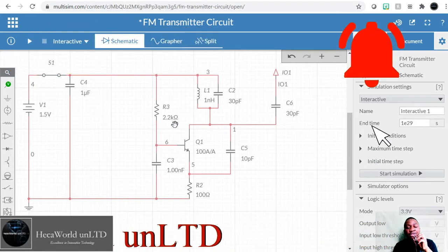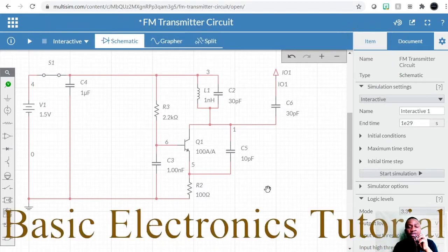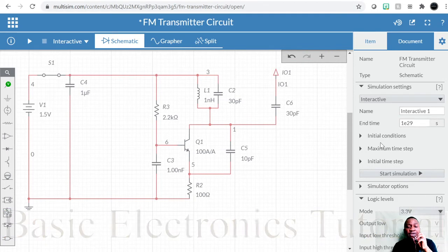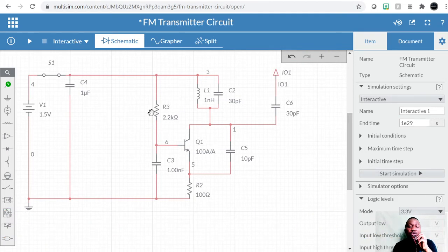The most important thing here is that you bias your transistor. So do this the way we did it. When we did it the first time, we didn't have this simulator, so we used a 10 kilo ohm trimmer resistor here and trimmed it until we got the transistor to turn on. The value that turned this transistor on was around 2.3 or 2.4 kilo ohms, and we found a practical value is 2.2 kilo ohms.